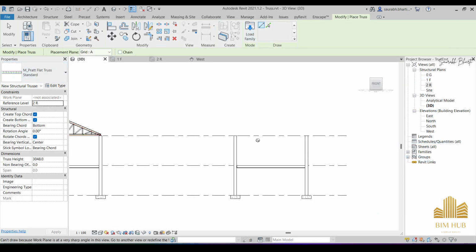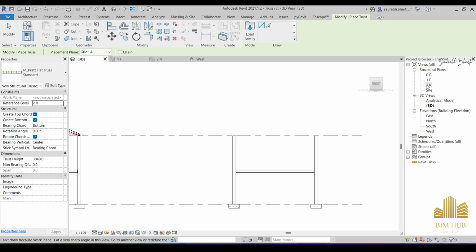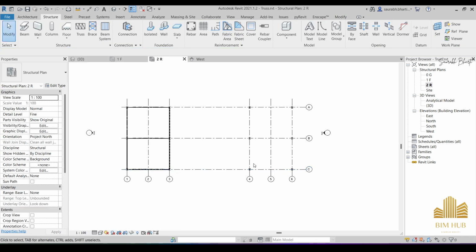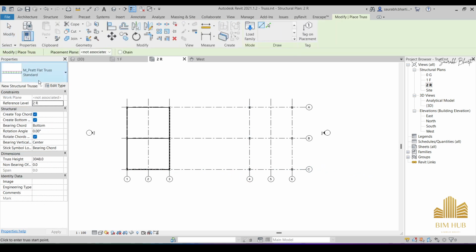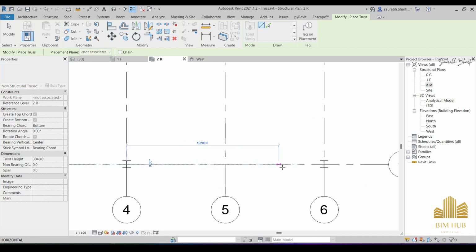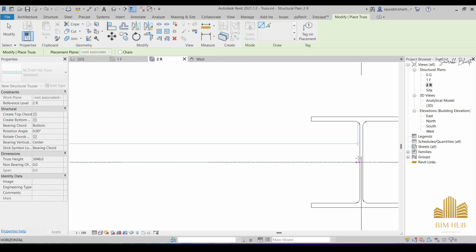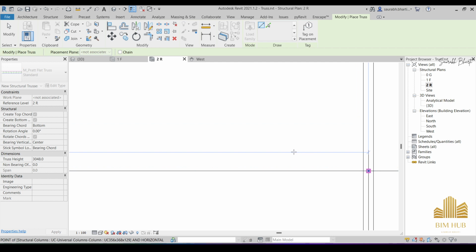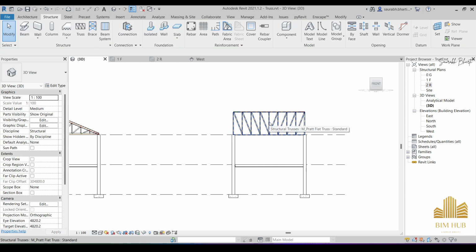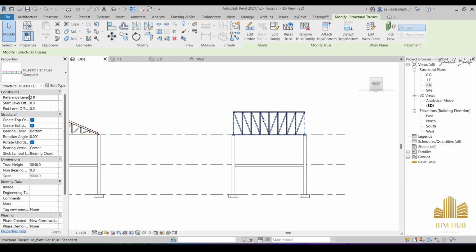After that you can just draw it in. Just go to the toolbar, and here we need to draw the truss. So select the truss, the emperor truss, and here, let's go to 3D view, and now as you can see the truss has been provided over here.